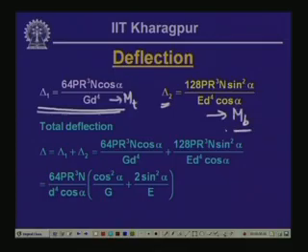And note that we have disregarded the deflection in the spring because of the axial tensile pull and the transverse shear, as we have seen that the effect of the tensile pull and the transverse shear is very small in comparison to the twisting moment and the bending moment. Accordingly, we have disregarded those components, and we have computed the value of the deflection exclusively for the twisting moment and the bending moment.